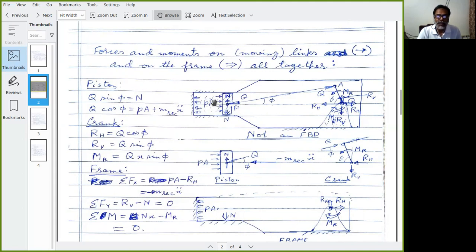So here you have the hot gas, I mean hot after combustion, which has a pressure, and it applies the same pressure in all directions. Now, at the left end, as the figure shows, this force, the pressure into the cross-section area of the cylinder, PA, operates on the cylinder head, and at this end it operates on the piston.